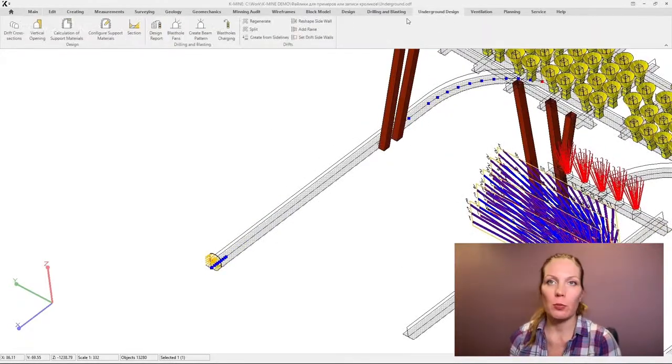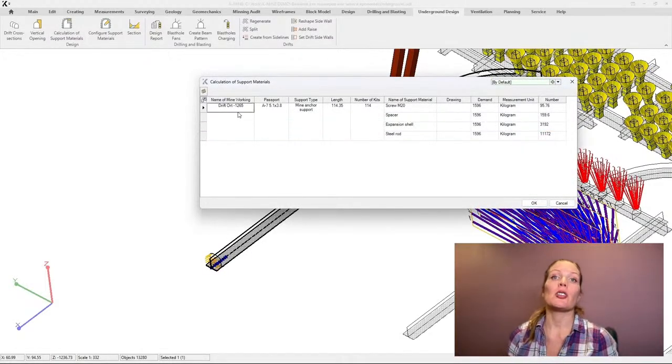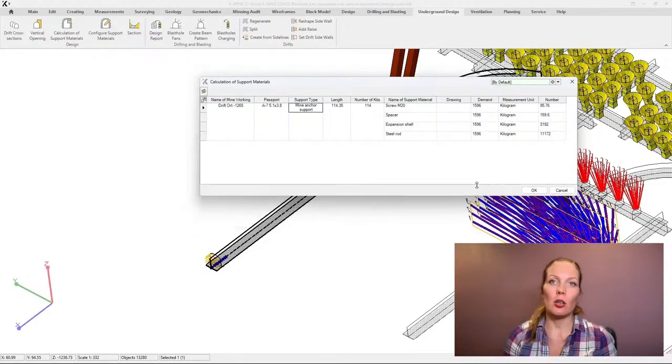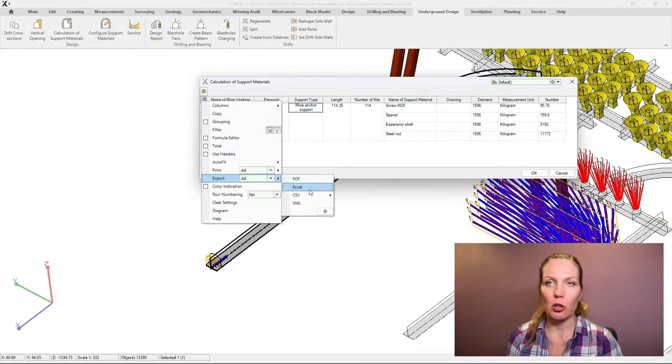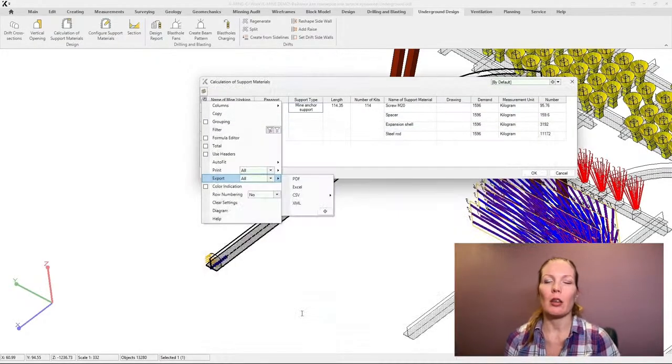So this allows controlled updates. If the stope changes slightly, regenerate only the attached crosscut. If it changes significantly, then flag it for redesign. If only its economic parameters change, then pass those to scheduling and keep the geometry intact. The tolerance for automatic updates depends on the method.